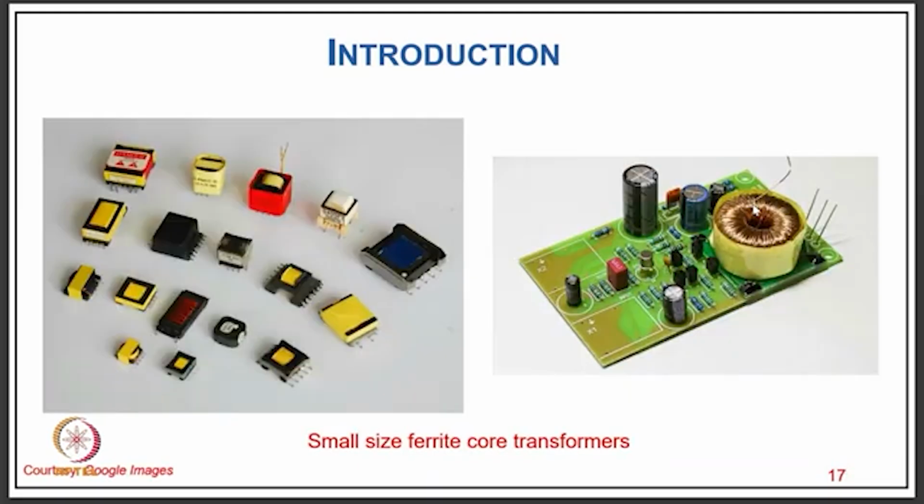You have typically a lot of transformers for high frequency applications, like those used in power electronics and electronics transformers, which are normally made with a ferrite core, not with laminated steel, because the power is of course low. Apart from that, we go for high frequency. The size of the transformer is reduced because of high frequency for the same amount of power. There are plenty of applications of this, and day by day the applications of such high frequency transformers are increasing.